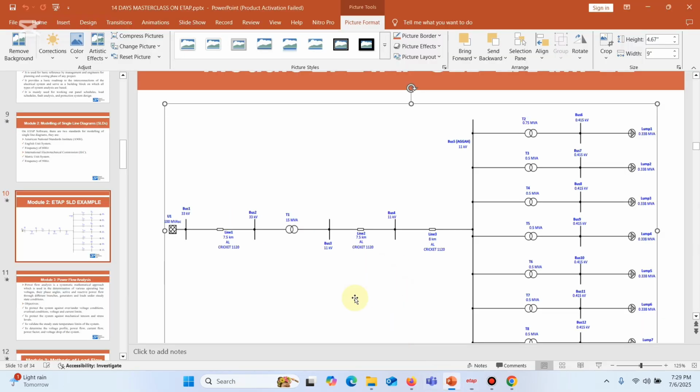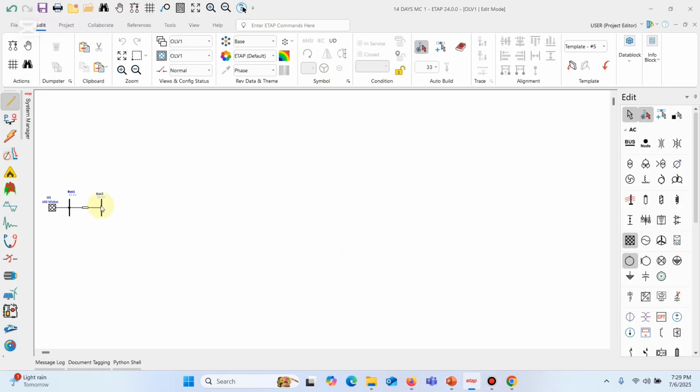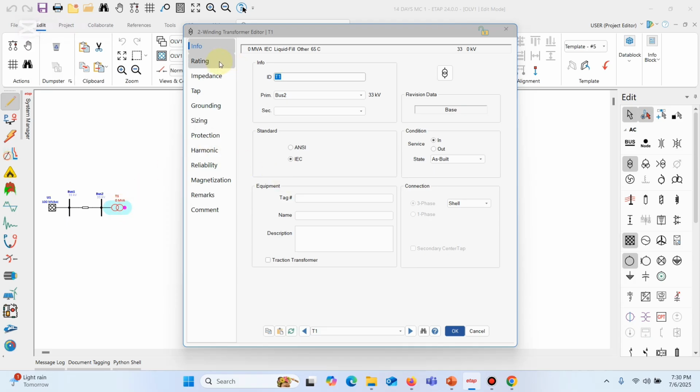Following our single line diagram, we have a 15 MVA transformer next. A 15 MVA transformer to a bus bar, bus 3. So we come over to our software and repeat. Click on the bus, a 2-winding transformer, and we can move the ratings over here. Then we open the transformer by double clicking on it, go to the rating page.